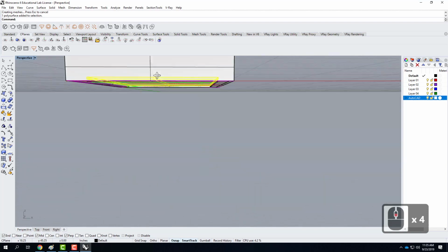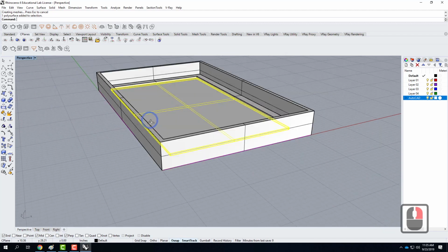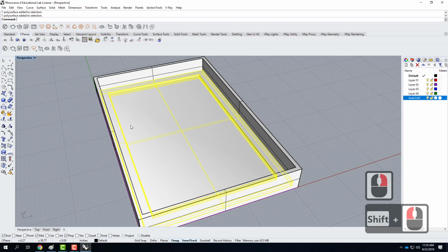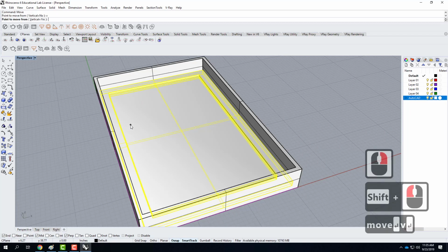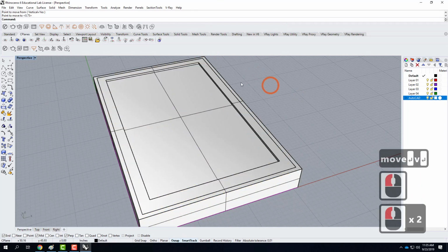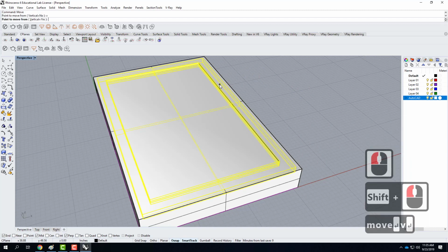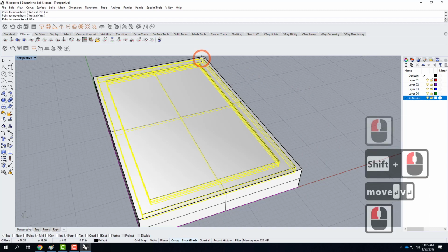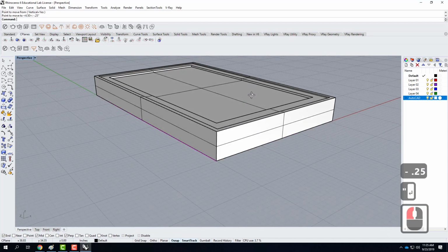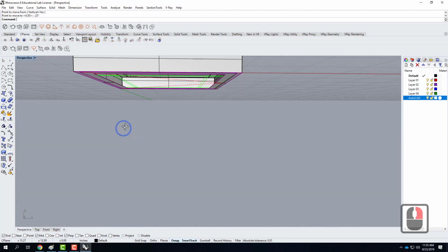So next thing, I probably need to move this window toward the outside of my window. So I'll take the glass, and I'll take the frame here. Let me go ahead and move it, V for vertical, and I'll pull it up so that it's even with the outside of the window. In all reality, it probably has a little bit of a reveal to it there. So let me move vertical, and we'll say maybe negative 0.25 inches. So it has just a little bit of a reveal to it. So I now have that established.